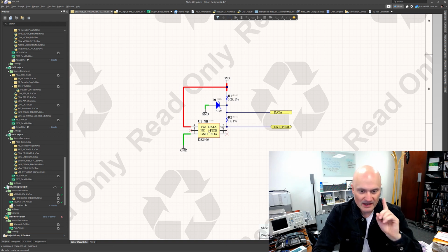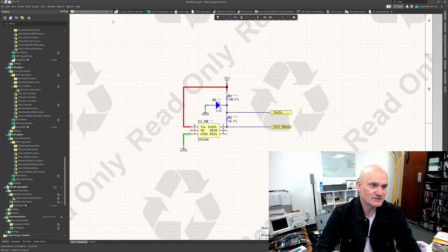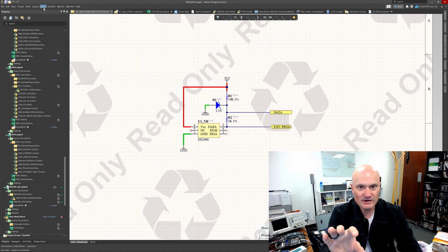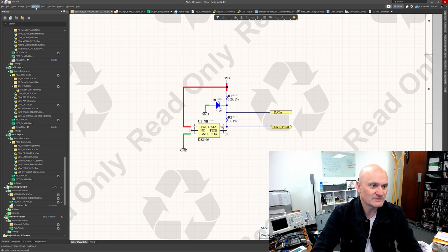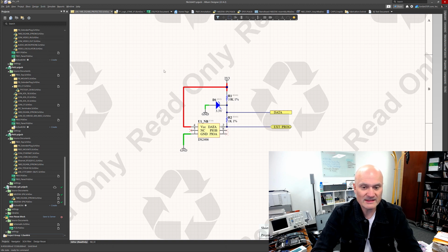And so a couple of things we want to be able to do here. Just to show you how it's connected through on the board side, this has actually already been routed on the board, this bit of circuitry. And so I might want to make sure on the Tools menu that Cross Select mode is on. And just to understand where these devices are on the board, I don't want to grab the 3v3 or ground nets and highlight those because they're everywhere, and ground and power planes.